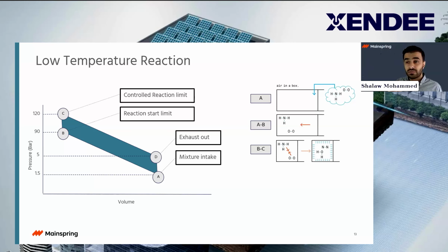And why is homogeneous important? Because in the case of an engine, the way combustion works, it expands out. You have a spot where the spark or the combustion happens and it just expands out. Well, that spot right there actually starts to create a lot of NOx. But in our case, because it's homogeneous and low temperature, little traces of NOx are produced, almost close to zero, near zero.